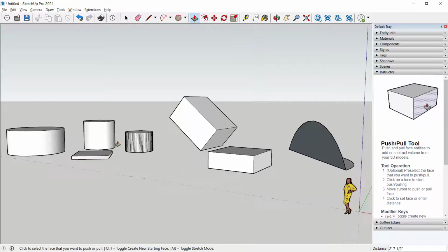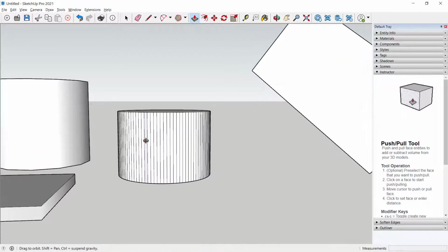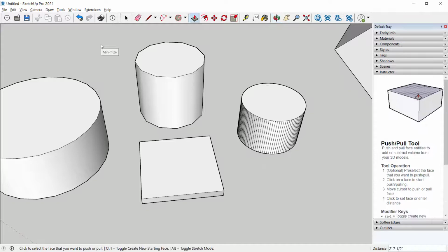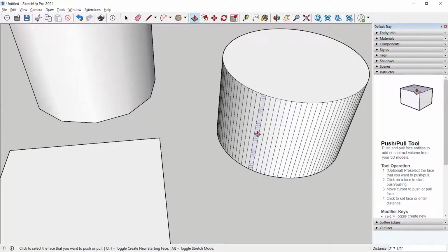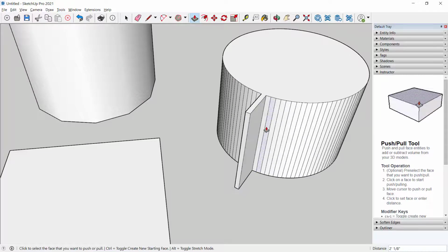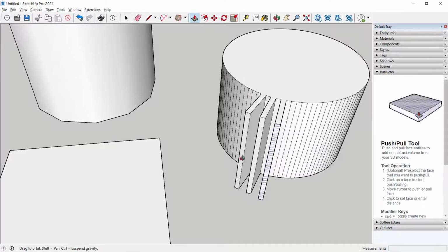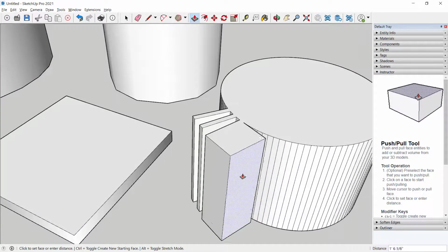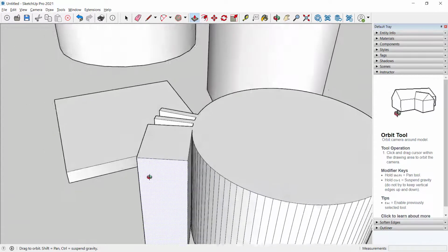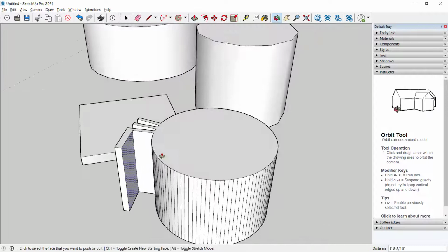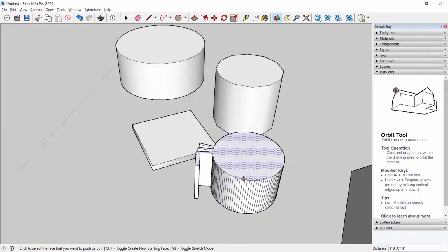And you might say, well, why does this one have lines? Just so happens that because I created it with the polygon tool, it does draw in those edge lines because sometimes they're useful. What's fun about that is you can actually push-pull those surfaces and create some pretty funky shapes. And in fact, the shapes that you push-pull, you can push-pull those shapes. So there's all sorts of options for how you can create different objects. In this case, push-pull is very effective.